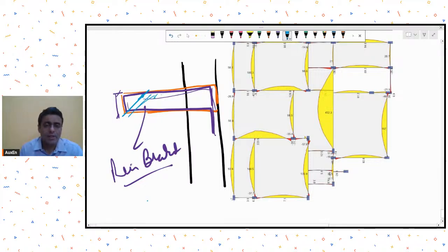So in colloquial language, this bracket in the place where we live is called a todi. It's a hidden bracket that we have taken out from the face of the column just to support a beam which was not concentric with the center line of the column. So we call this type of reinforcement bracket a todi. So maybe you can do it that way. And for analysis in ETABS, as I told you, you may use the option of a rigid link.